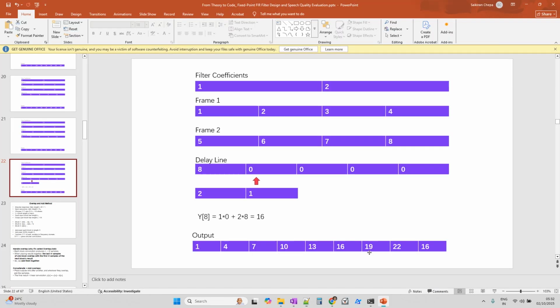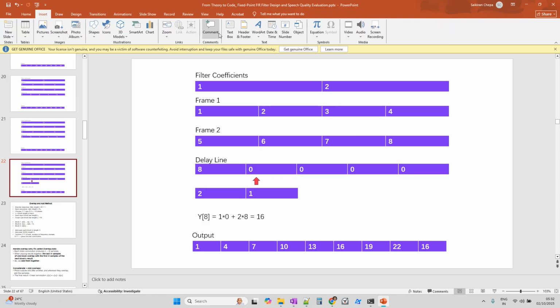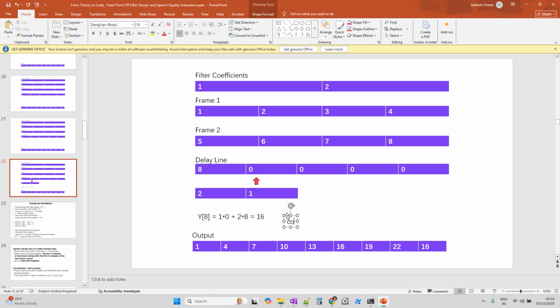So if you want to fix the Q format of the coefficients, we cannot fix it as Q1.14, because we have to add all these ones together. The sum is 3, which is greater than 2, so the next nearest number is 4. So 2 integer bits and 13 fractional bits is what we have to keep.